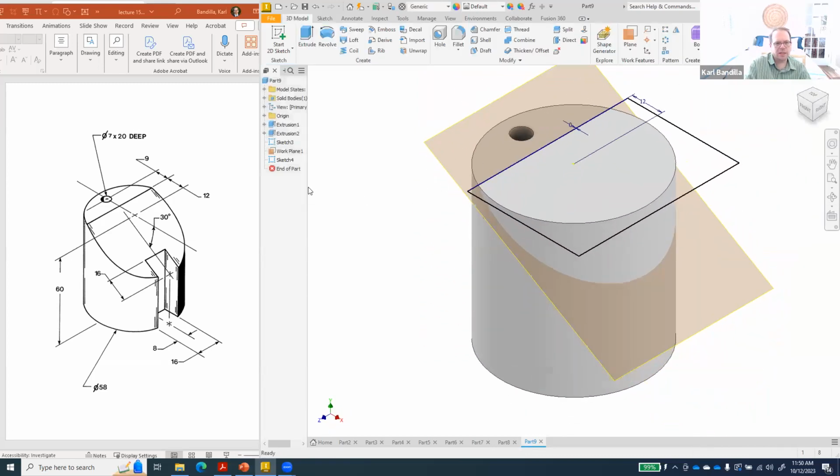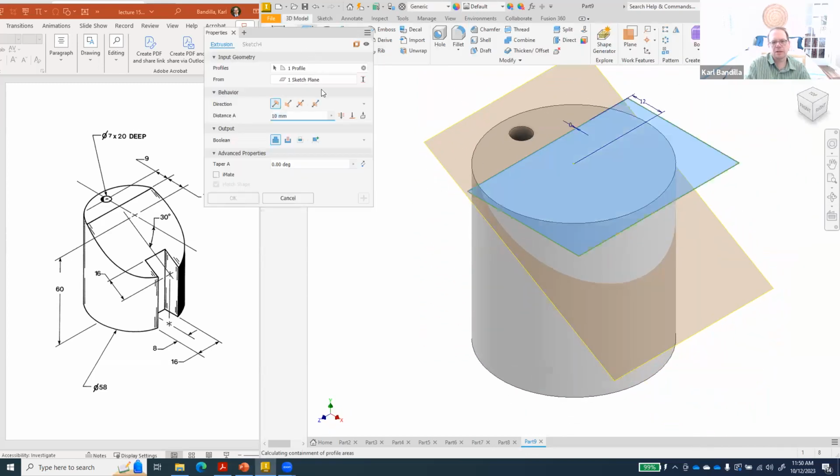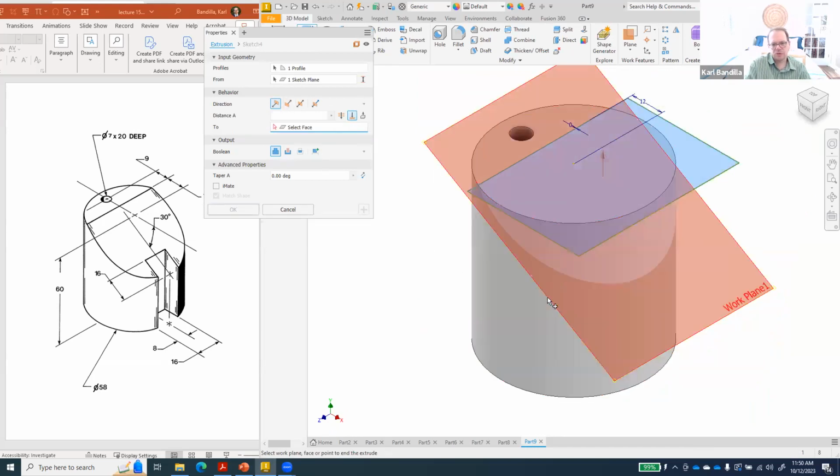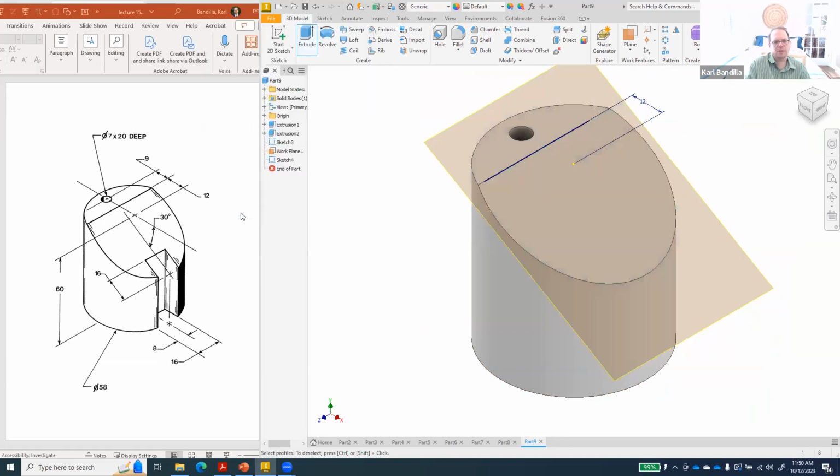And finish, and now we should be able to choose this work plane and cut, and it seems to be doing it correctly. There we go. Now we have our cutoff plane right here. So all that we're missing is this little notch. Again, the problem is that we don't know what the horizontal distance is. We can't just draw onto this one and cut, because then it's going to cut diagonally in. We want to have it cut down there.